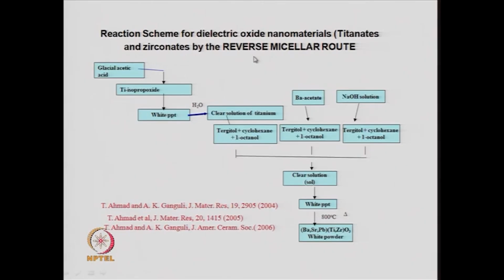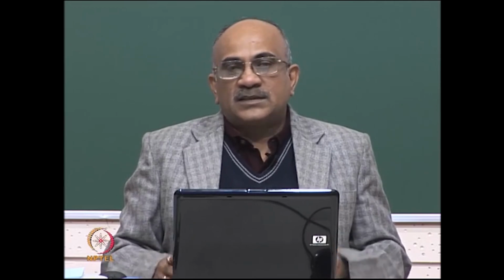So, this is one chemical route by which nanoparticles of barium titanium oxide, which is one of the most famous dielectric materials and is also a ferroelectric, have been synthesized. By a similar method, strontium titanium oxide, which is another important dielectric material, can be synthesized in nanometer-size dimensions. Similarly, lead titanate, lead zirconate and many other compounds which have important dielectric properties can be obtained, and they can be obtained in the nano-sized range.